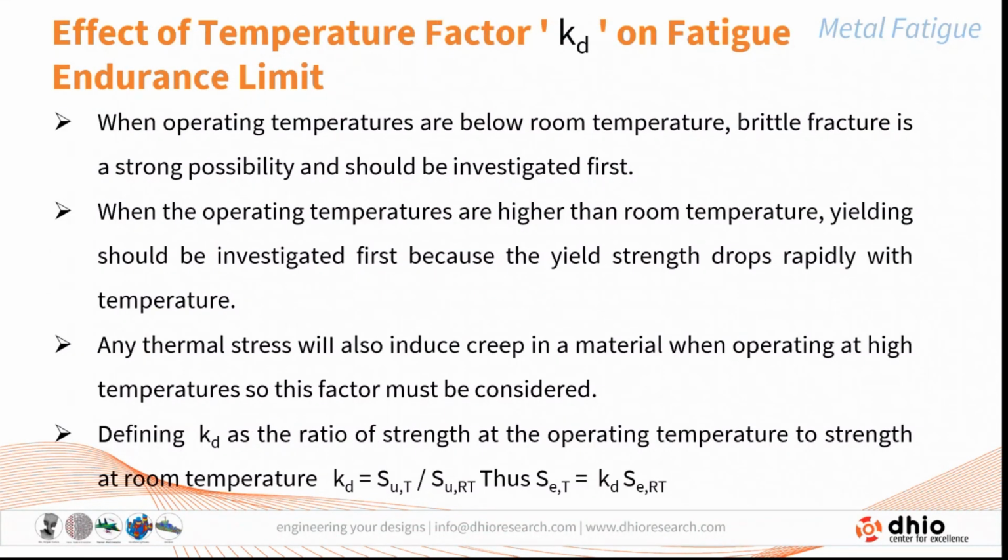Then the temperature factor Kd. Whenever the operating temperatures are below room temperature, we find that brittle fracture is a strong possibility, and that should be investigated first. But when the operating temperatures are higher than room temperature, yielding should be investigated first, because the yield strength drops rapidly with temperature.